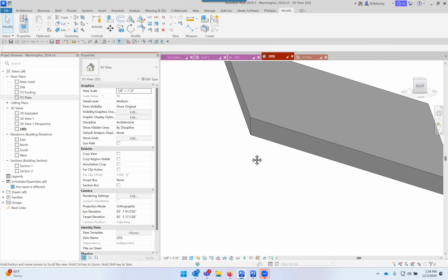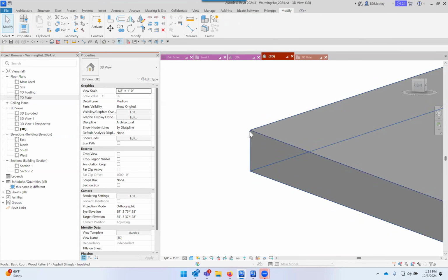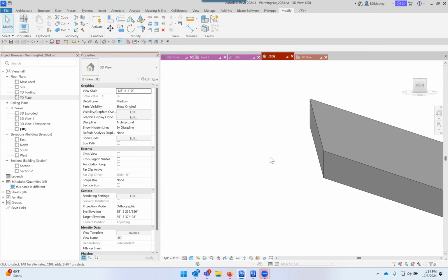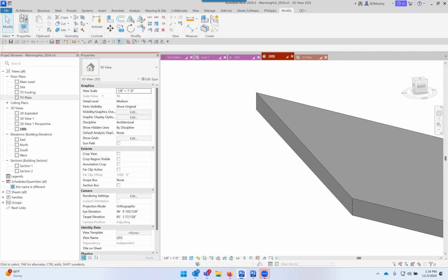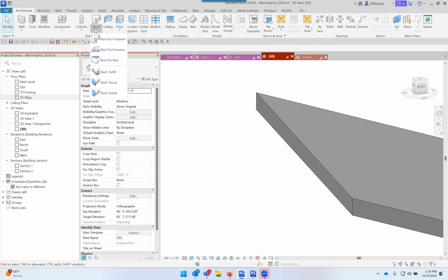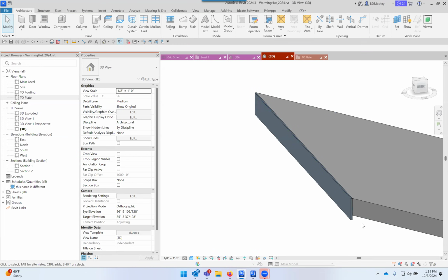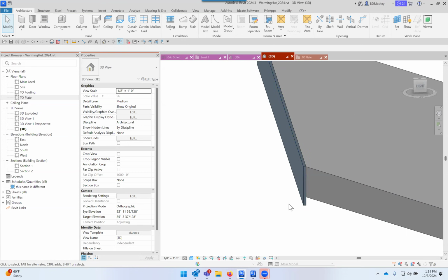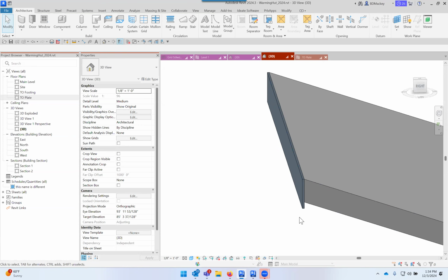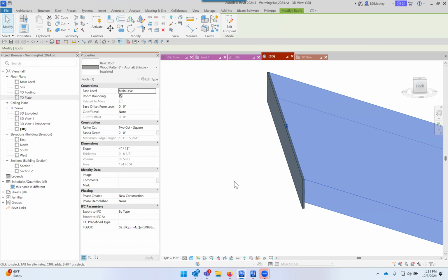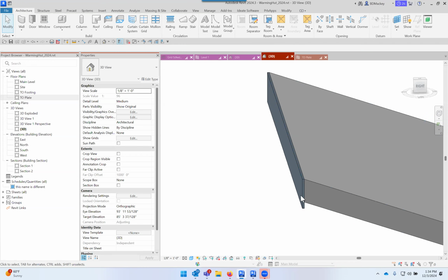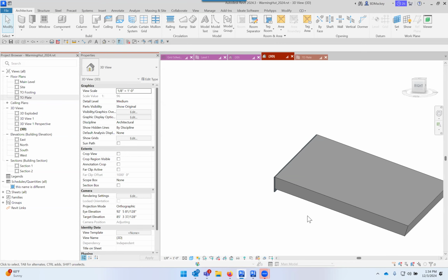You could, it would require a whole bunch of different things. You could put a fascia on here that had a triangle profile and sweep it along the edge. In your roof drop down, you'd choose to do a fascia. You could have that fascia be a wedge shape. Obviously, a 4/12 versus a 6/12 versus a 9/12 would be different sweeps, but you would be able to set that up with a fascia and then just assign it the same material. That's the workaround if you truly want to get that displayed.